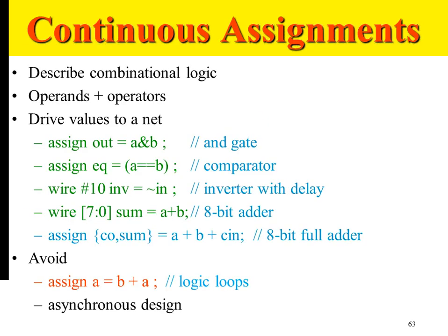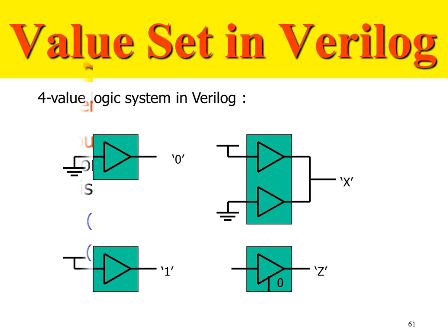Oh, okay, yeah. That's a guideline. Let me take a module example that we have seen. In this case, we declared input and then output. It doesn't matter. What you have read is a guideline that some designers will follow, where the outputs are declared first and then the inputs. But that's not a requirement. That's not a language requirement. I can declare inputs first and then outputs. Doesn't matter.